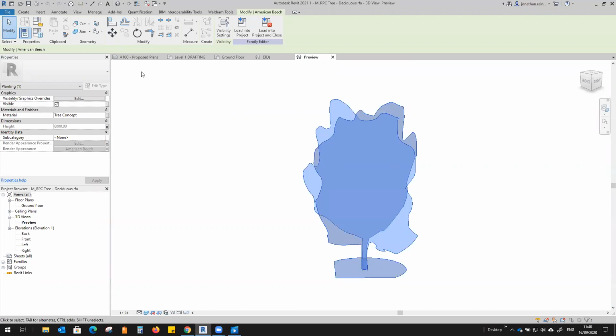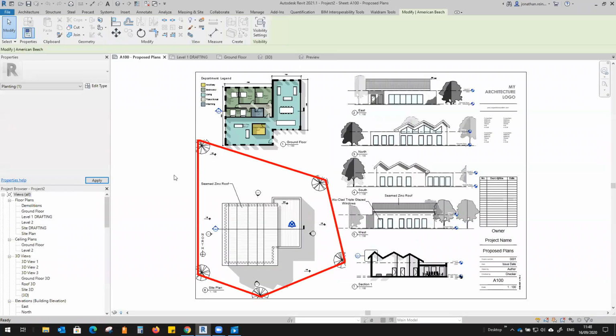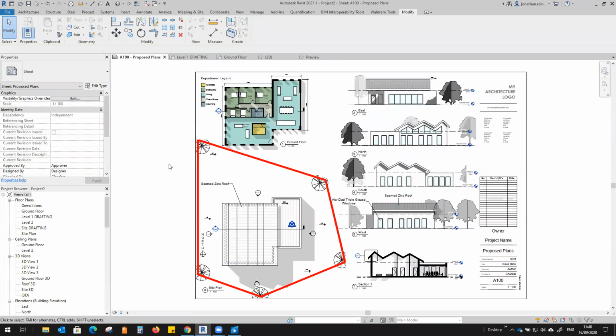Yeah, and is that the shaded view only, or when you change the other different views, is that any view, any of those options when you change the material? So that's only the shaded view. If your appearance tab is left blank in your materials library, then it will only pull in whatever color you've put in there. But if it's a realistic view, you can add in an image that only appears in a realistic view but won't appear in a shaded view.